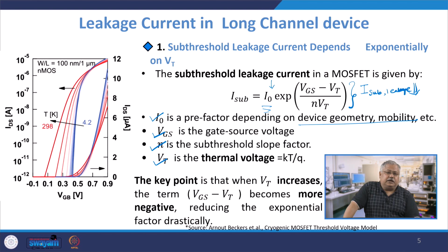and that comes as a savior in terms of power dissipation naturally. So, this has nothing to do with any of the changes we are trying to make on the leakage path, but ordinarily just by looking at the value of VGS minus VTH, you can find out the value. Let me name this VTH because there will be confusion here. VTH is the threshold voltage, and VT is KT by Q, which is 25 millivolts at 300 Kelvin.